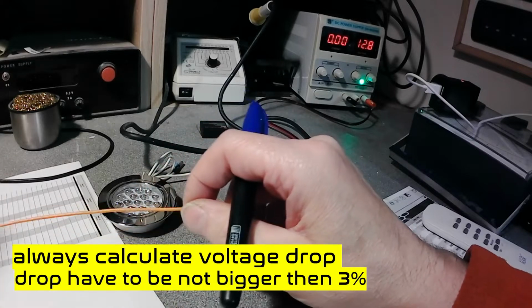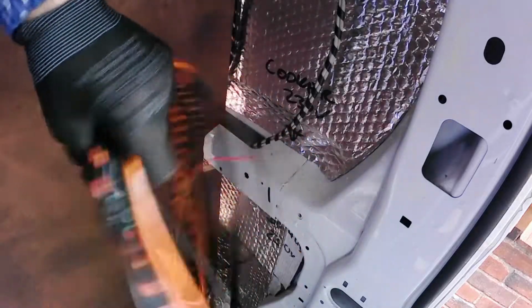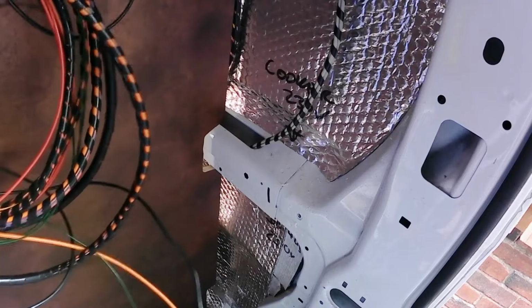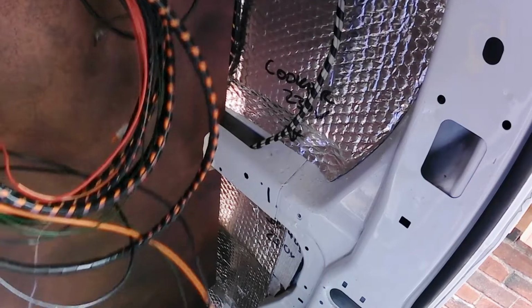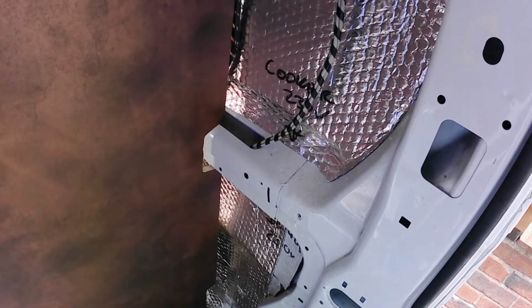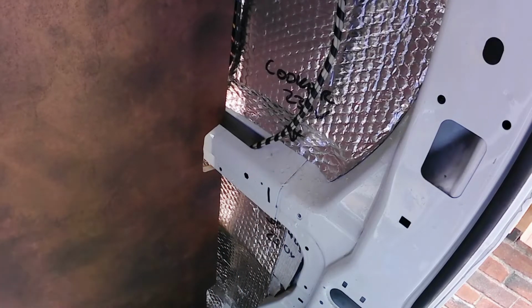It means it's not in a harness with other wires, but alone in the air at a standard temperature of around 25 degrees Celsius. So when we put this small wire into the harness, every wire carries some current and heats this wire.